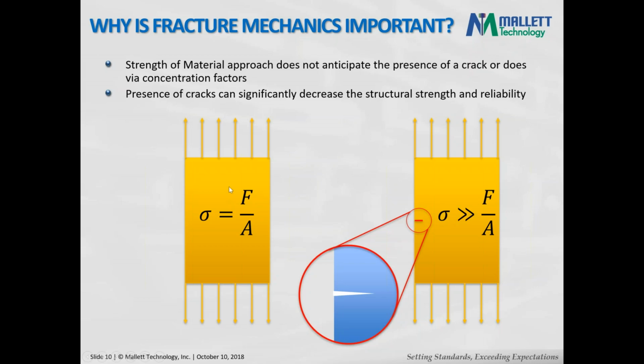As you know, when we apply force on a flat panel, the stress in the regular strength of materials approach can be easily calculated by force divided by the cross-sectional area. But when you put in a crack, right at the crack tip, the stress goes to infinity.